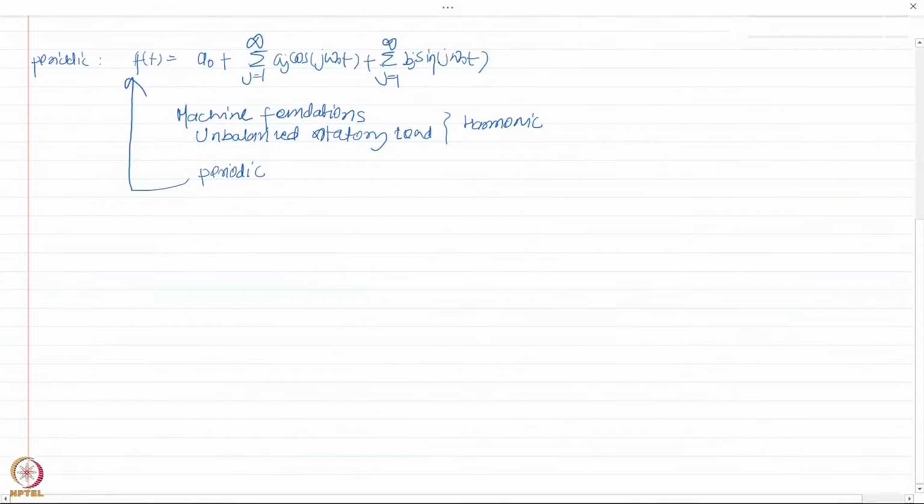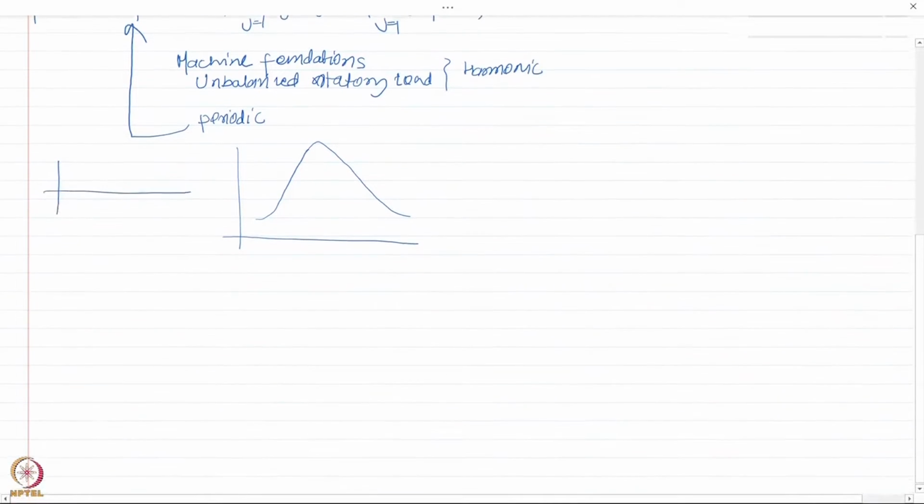So earthquake in reality might be a random excitation. It is composed of several frequencies, and you will see that later when we get into that. There is a term called power spectral density, which basically defines how much energy is situated at each of these frequencies.